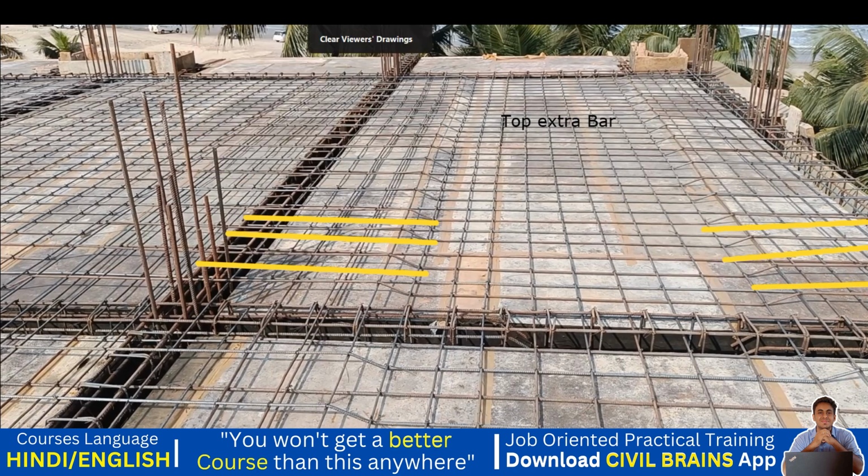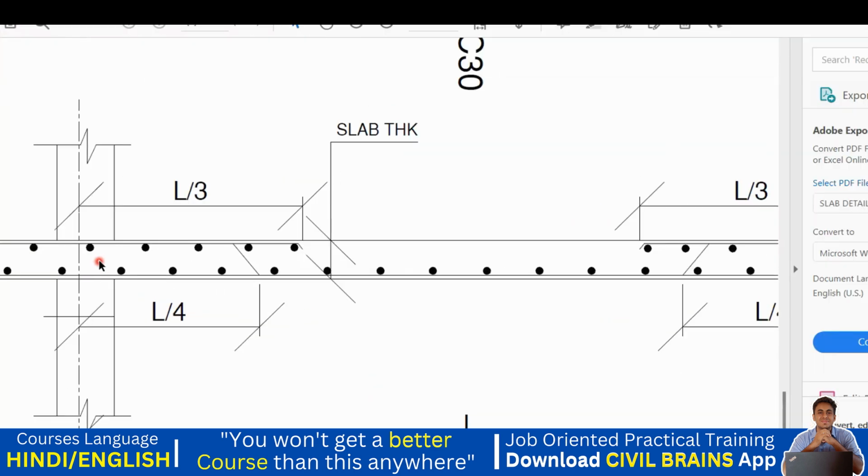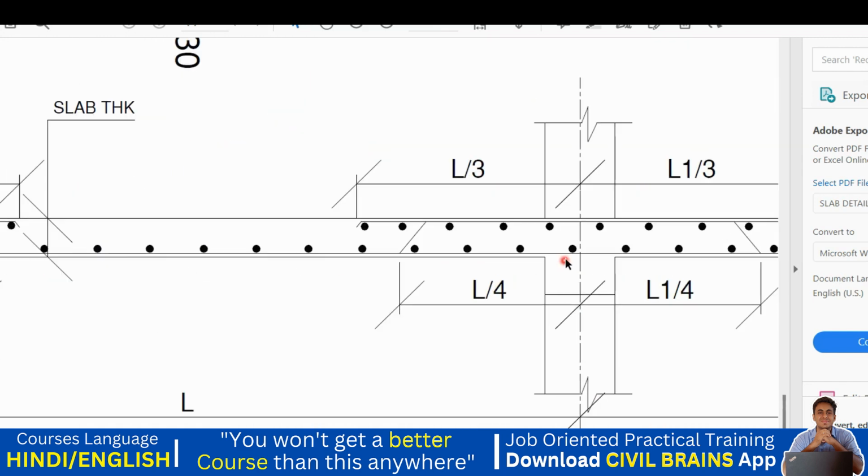And where is the reference for that? The reference for that is, I'll go to the structural drawing, and you can see here something they have mentioned here. What is this? You can see this bar. And what is the distance mentioned? It is L/3. So this bar, whatever they have mentioned here, that is called your top extra bar.